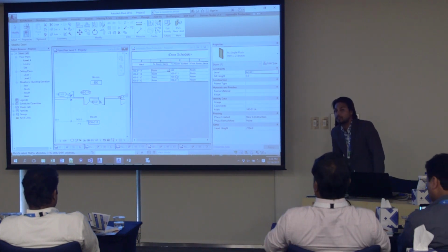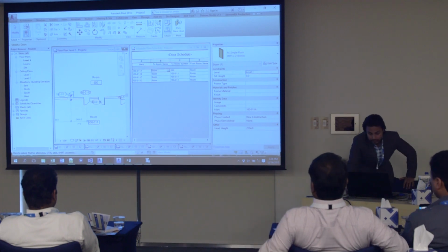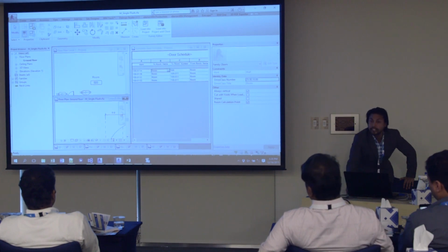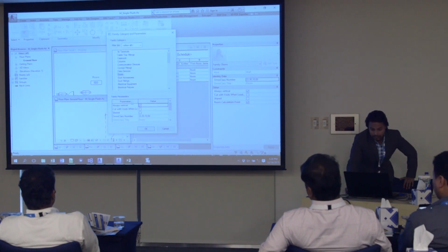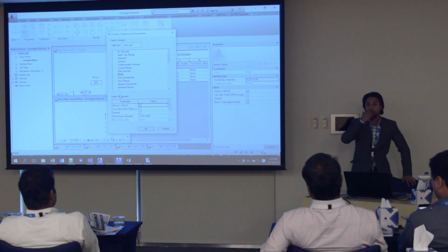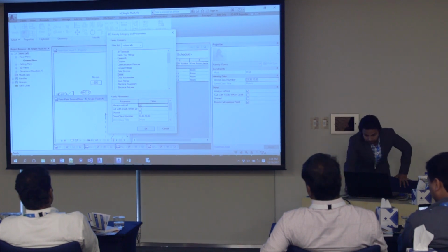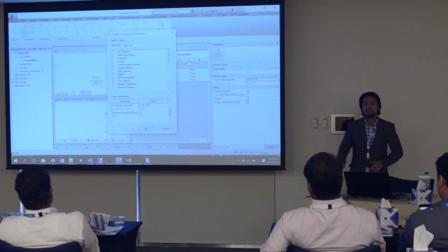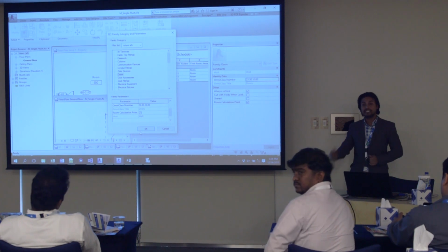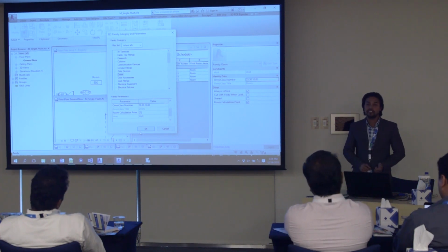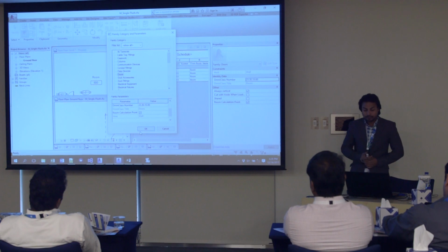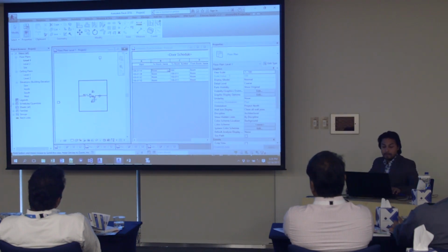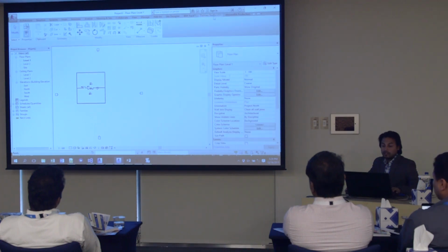Sorry? Yeah, if I edit this family, go back here to the family category and parameters on the top. Here I have another set of extra parameters that actually pretty much handles behavior. Here is the one which is the room calculation point. So furniture, every individual element, you can schedule it. If you don't have that particular parameter scheduled, it won't eventually. So yep, we have this, and so all right, it does it.